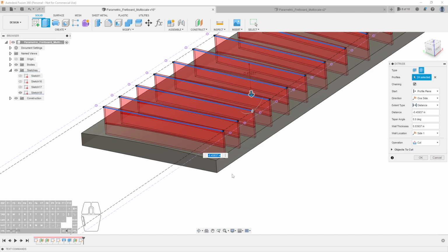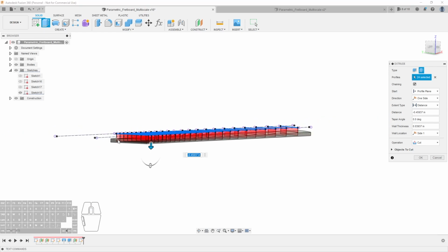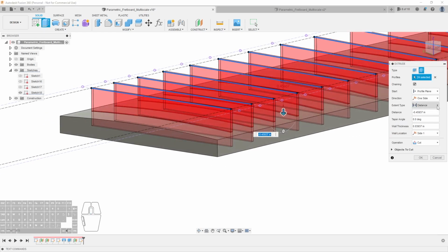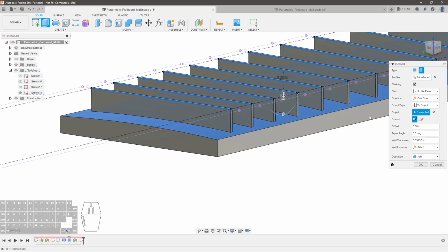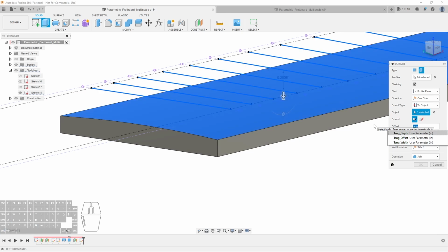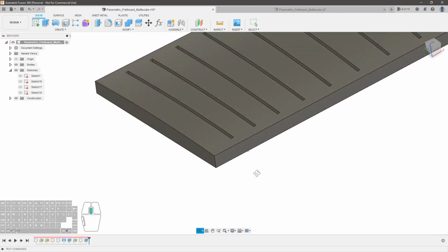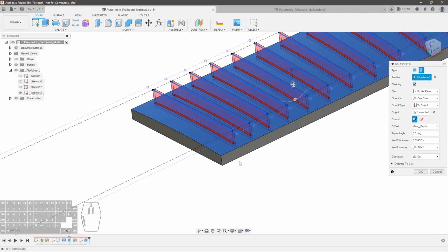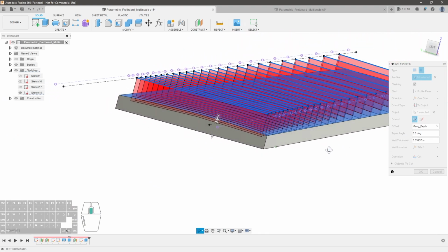Now, here's a challenge that I ran into when developing this compound radius. In my original video, what I did was set the extent type to object, that surface, and then I did a negative offset. So we'll do a negative offset of minus tang depth. And that actually worked in this case because we're inside the extent of the fretboard and we maintained our radius.